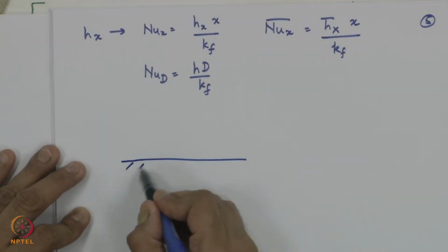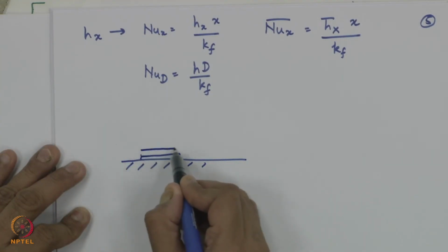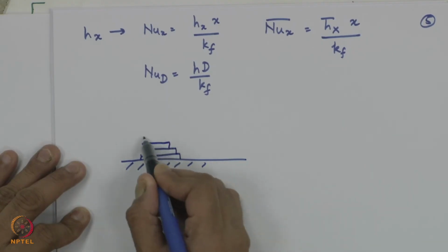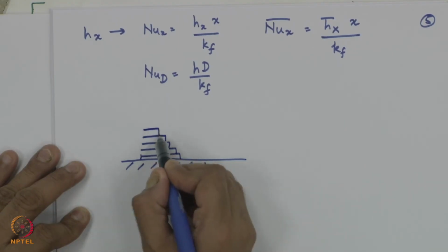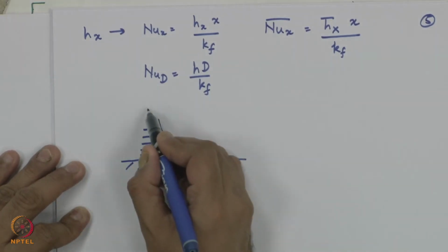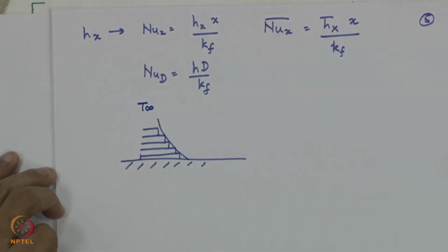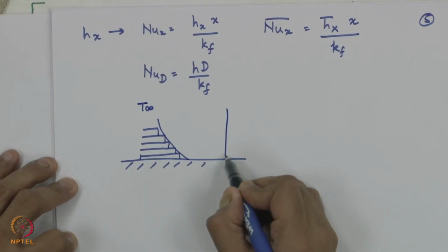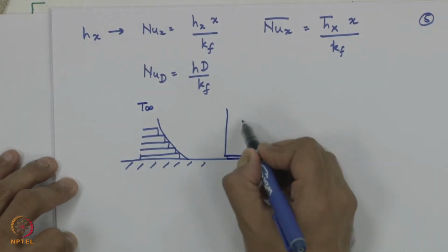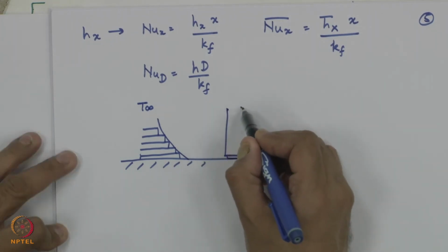So, there is going to be a temperature gradient, as you would see, and that is what we have drawn repeatedly. This is the flat plate, a layer of the fluid which is at T wall, next layer something different, it is highly exaggerated. What I am trying to show is the development of this so called thermal boundary layer. So, this point where the temperature almost is equal to T infinity, further along, this is going to become larger, it is going to take a greater distance in the y direction for the fluid to reach T infinity.